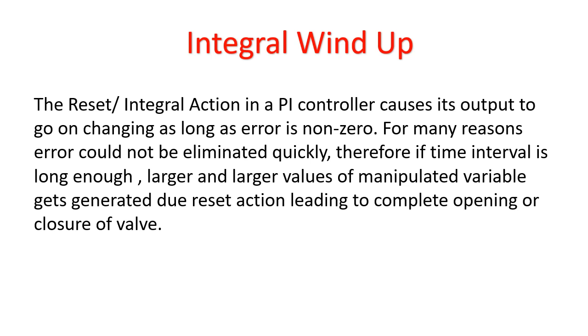So what is integral control? We know that integral control, or reset action, acts on the error as long as the error is not zero. This is the property of integral action, and this helps to eliminate the error. But on the other hand, if the error could not be eliminated totally, then as the error is non-zero, the integral action continues to act upon it.